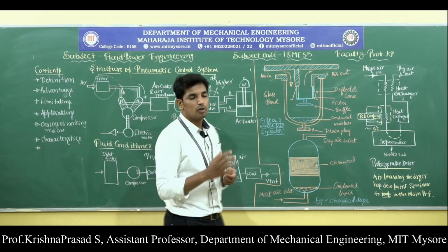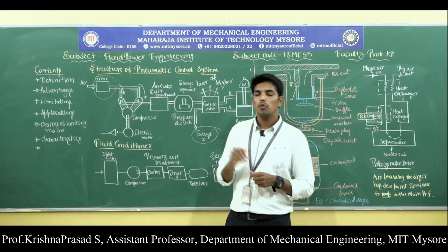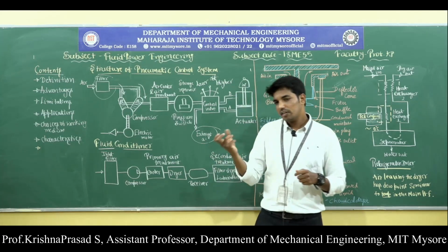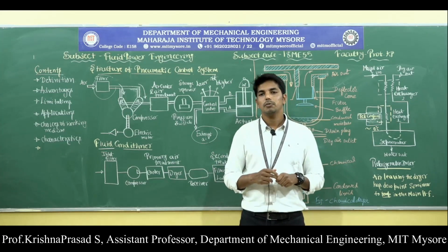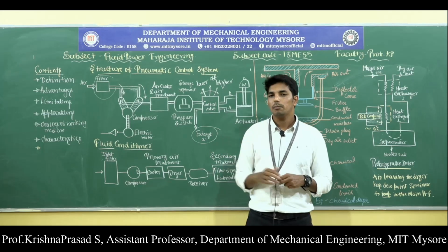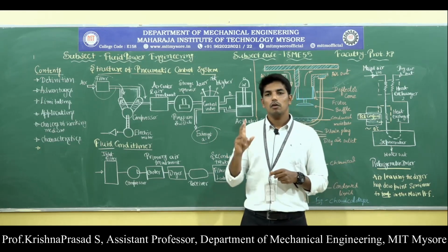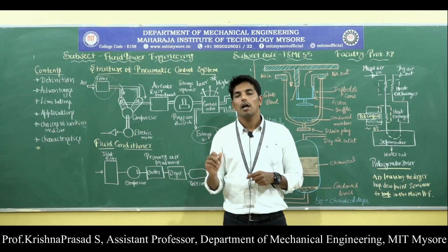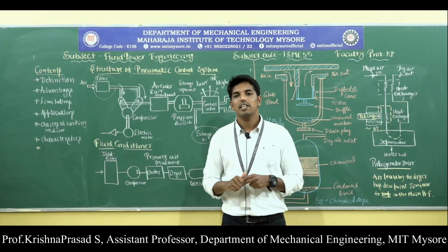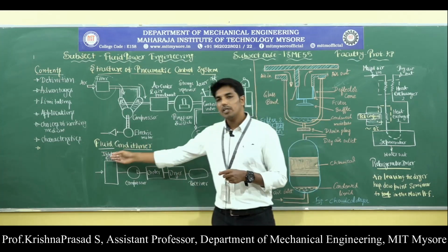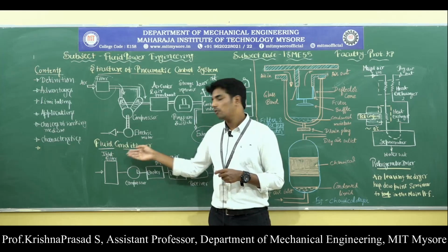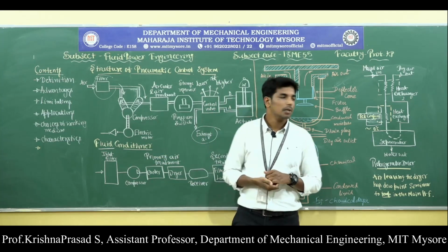Very important one: why do we need to filter the air? Whatever air we are going to use in the pneumatic system should be clean and dry. It should be free from contaminants like water molecules, oil, as well as dirt and dust particles. That's why preparation of the compressed air through this fluid conditioner unit is very important.